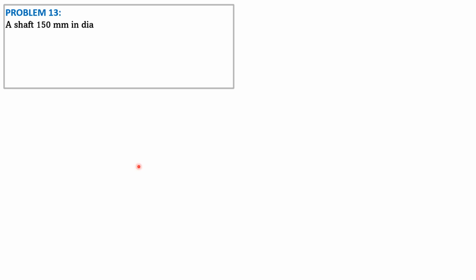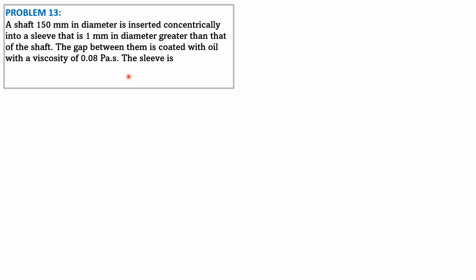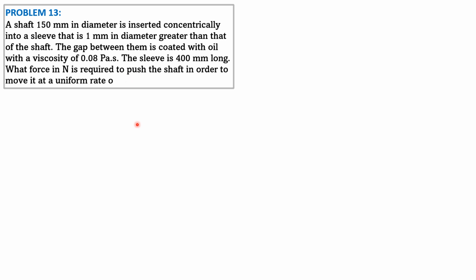Problem 13. A shaft 150 mm in diameter is inserted concentrically into a sleeve that is 1 mm in diameter greater than that of the shaft. The gap between them is coated with oil with a viscosity of 0.08 Pascal second. The sleeve is 400 mm long. So what force in newtons is required to push the shaft in order to move it at a uniform rate of 0.6 meter per second?